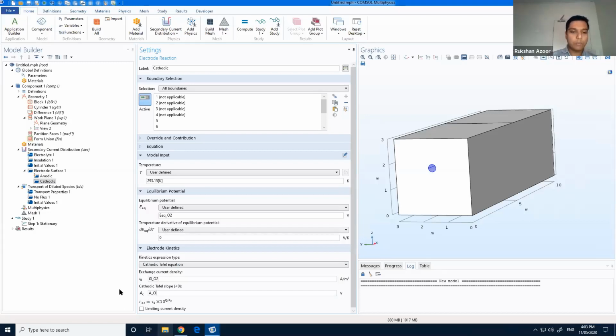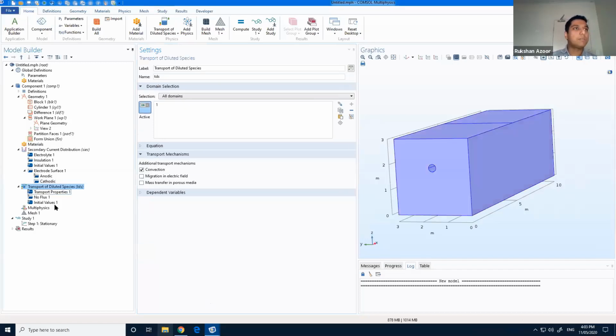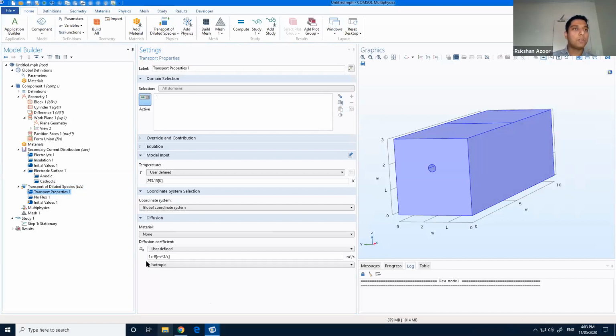So here we need to remember our coupling, which is C over C ref, multiplied by that. So you can type in that over there. And transfer value to species. At this point, we don't want convection. Transport properties. Let's give 1E minus 7.